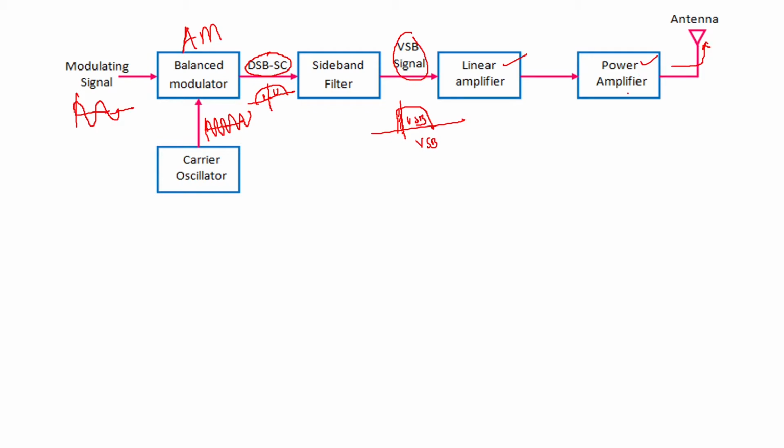Now here you are saving the bandwidth, and you are also saving the information of the lower frequencies. So this is how a vestigial sideband takes care of the lower frequencies. This vestigial sideband transmission in amplitude modulation is used to transmit the video signal. Only the video signal is going to go through vestigial sideband, whereas the sound signal will follow frequency modulation.